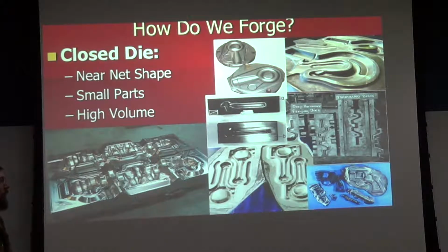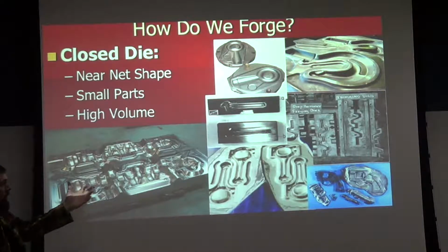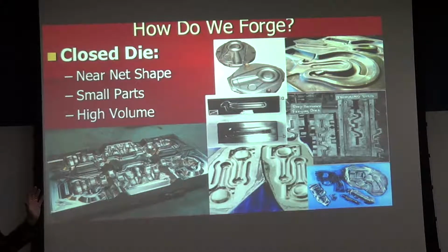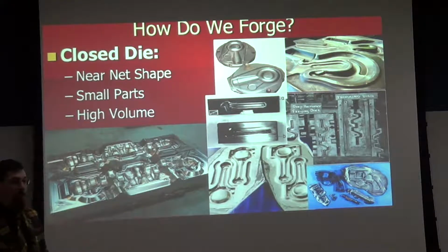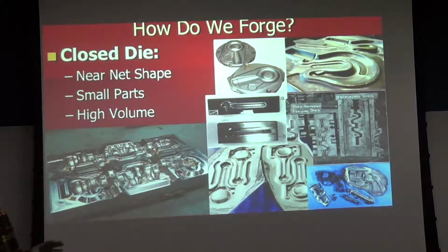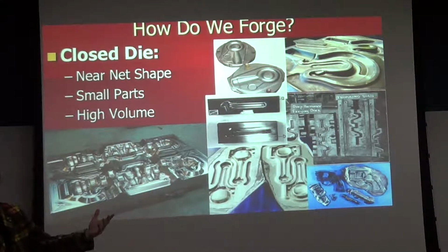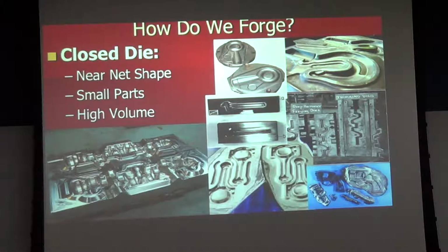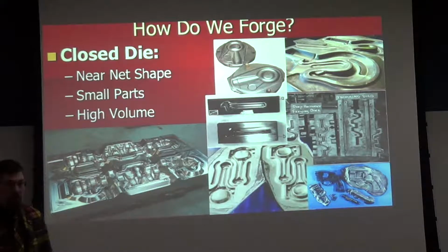So in this technique, you use a block of steel or some other material to create the negative of what you want, basically. And then you take your hot metal, put it in there, and when you pound it, the metal flows to fill all the cavities. Now, I say flows because it moves around, but it's not liquefied. This is a solid state deformation situation. Now, I mentioned that most of the tooling would be steel. There's some fun exceptions to that. There are times when forging is done with the tooling at the same temperature as the metal being forged.